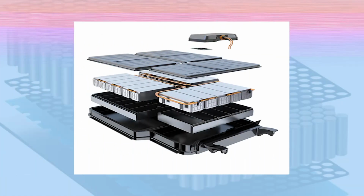The third kind of heat sink design is the complete fin. The complete PCB or the system in the converter will be mounted on the heat sink. The heat sink will be the base and will have high fins. The complete system will be on top, and the switch and diode in the converter will be pasted or inserted into this heat sink.